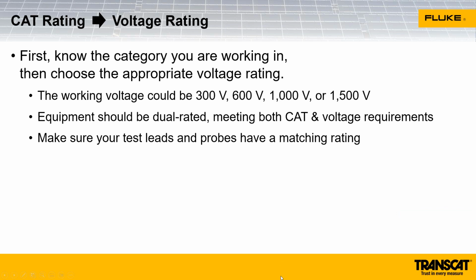So another thing that we need to think about is that the test leads we're using with our meter need to match the category voltage rating of the meter itself and the environment voltage we're working at. So for example, for a 1500 volt rated meter, make sure that you use the 1500 volt rated leads that come with the meter.